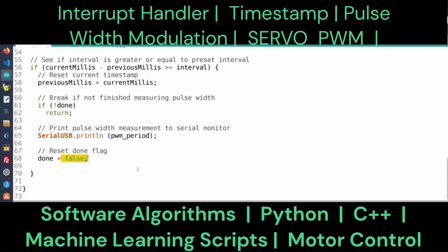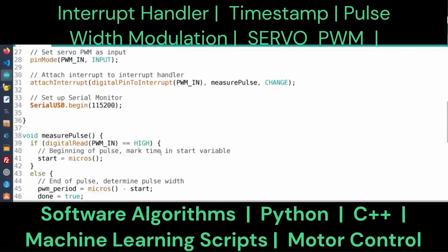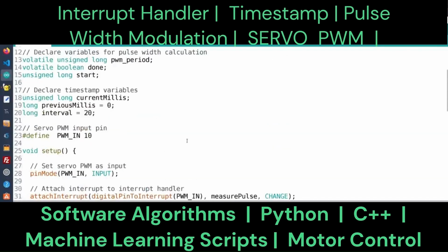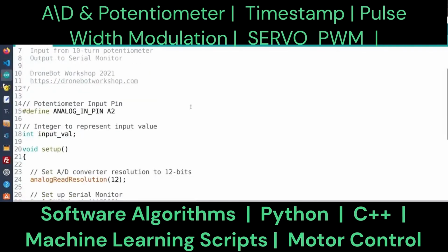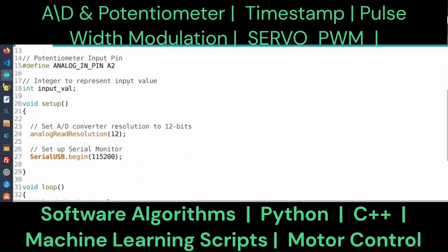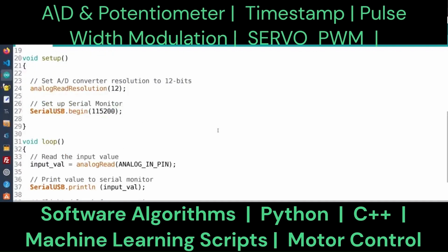Servo motor driver software methodology. So you need to include the PID library. Then set the PID gain variables by fine-tuning proportional gain, integral gain and derivative gain.